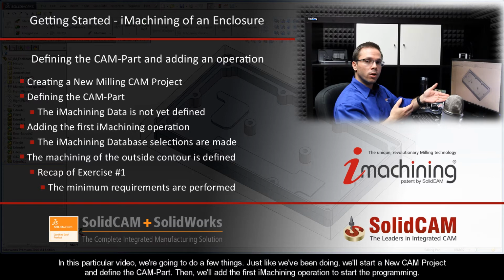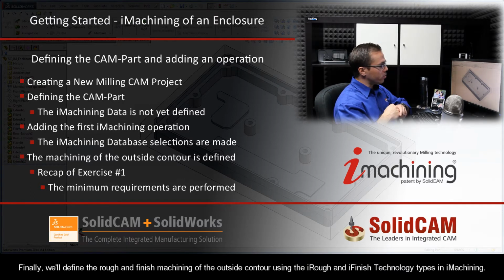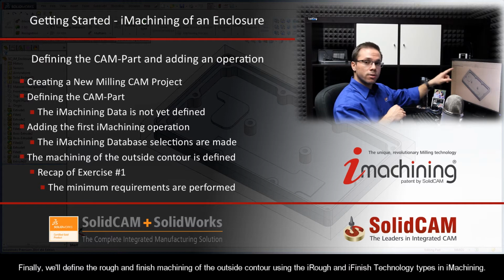Just like we've been doing, we'll start a new CAM project and define the CAM part. Then we'll add the first iMachining operation to start the programming. And during this process, I'll show you two different ways that the iMachining data can be defined for the CAM project. And finally, we'll define the rough and finish machining of the outside contour using the iRough and iFinish technology types in iMachining.